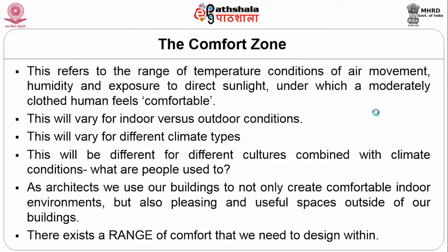So, comfort zone refers to the range of temperature, conditions of air movement, humidity and exposure to direct sunlight under which a moderately clothed human feels comfortable. This will definitely vary when we are considering outdoor versus indoor conditions. Also, this will vary because of different climatic zones like we just discussed. This will be different for different cultures, combined with different climatic conditions, what are those people used to in the general sense?